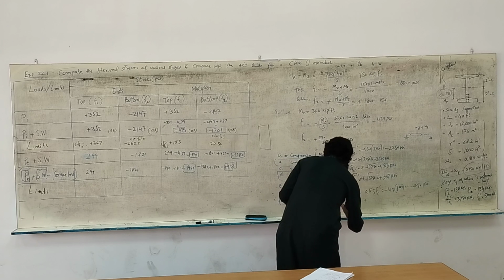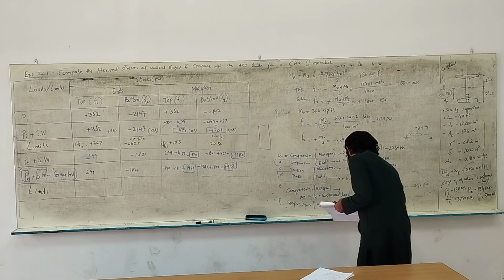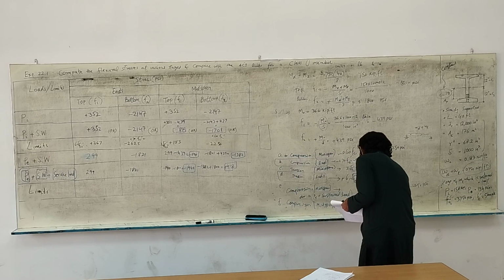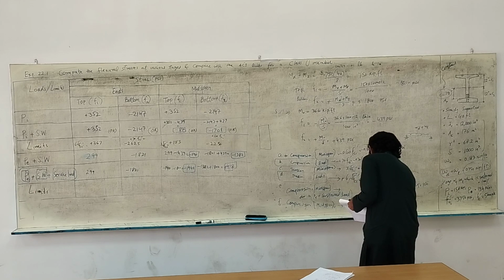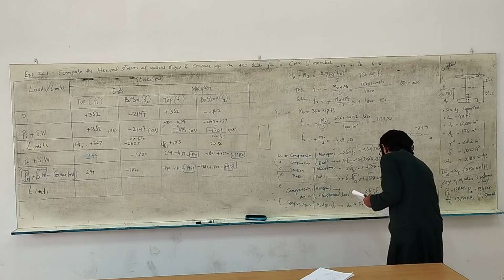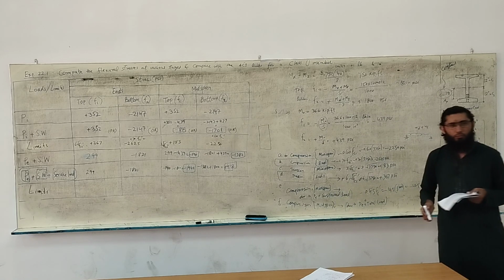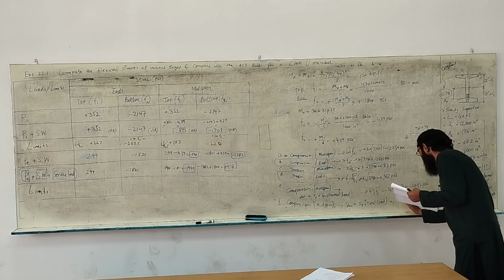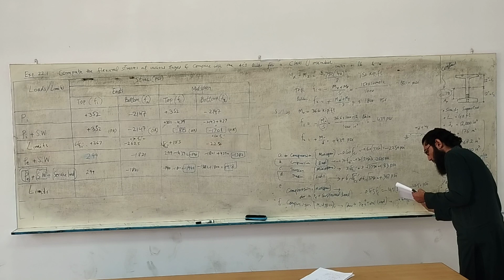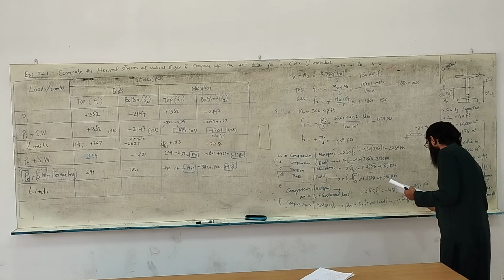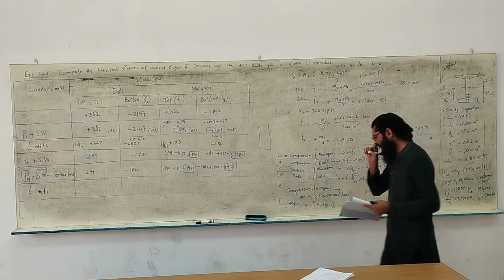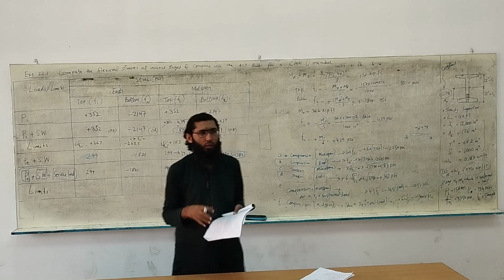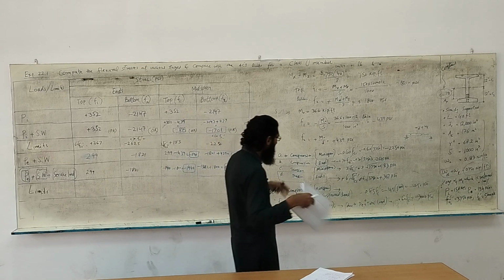Okay, total load, PE plus total load, and this limit was minus 0.60 fc prime, which happens to be minus 3000 psi. Now, since all of our loads are sustained load, total load is all sustained load,